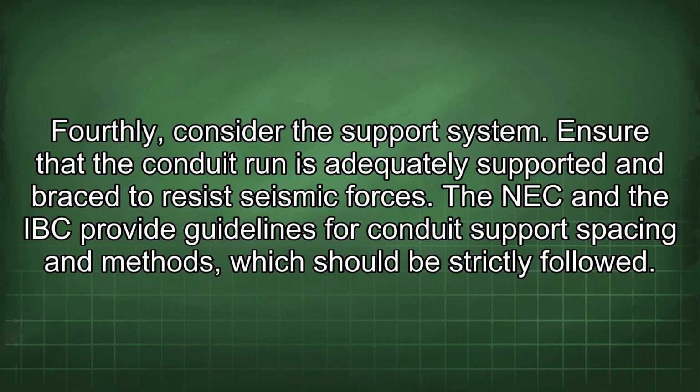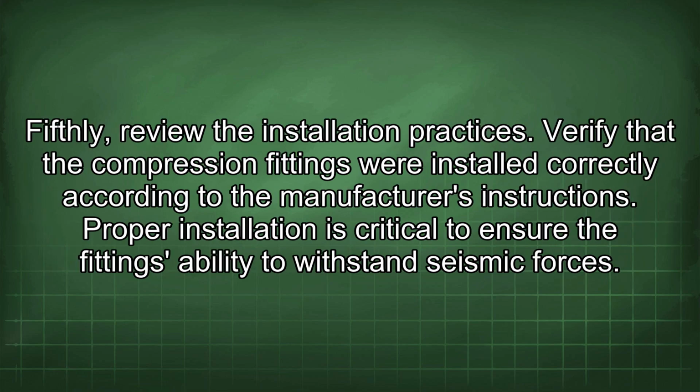Ensure that the conduit run is adequately supported and braced to resist seismic forces. The NEC and the IBC provide guidelines for conduit support spacing and methods, which should be strictly followed. Fifthly, review the installation practices. Verify that the compression fittings were installed correctly according to the manufacturer's instructions. Proper installation is critical to ensure the fitting's ability to withstand seismic forces.